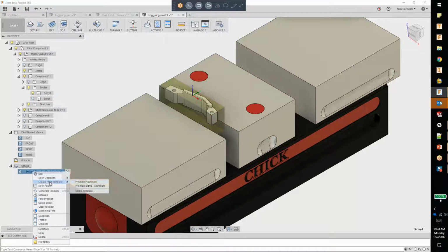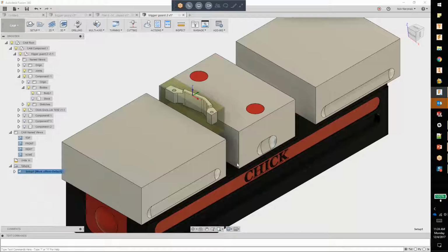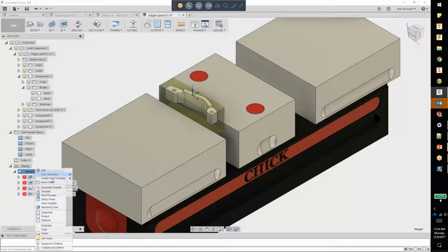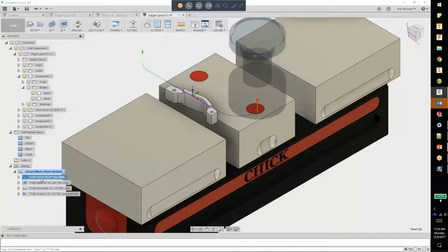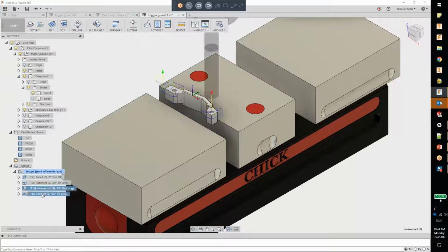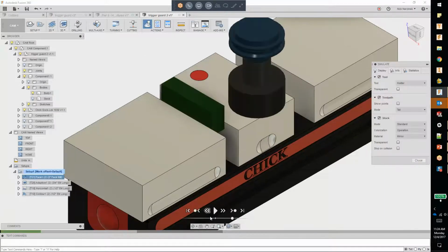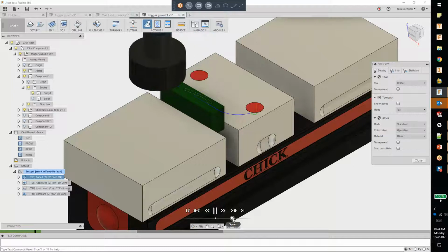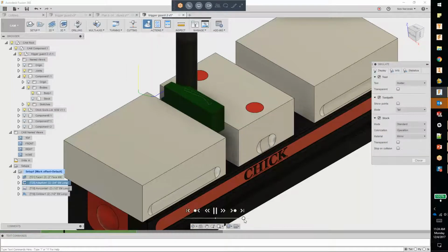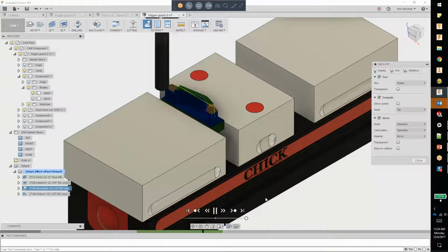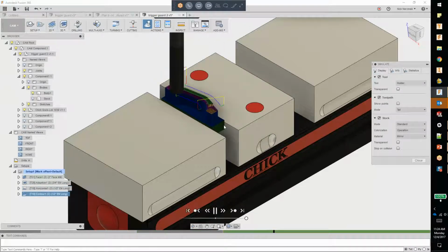And I've got some templates in here. I'm just going to create a template and regenerate those. It's probably not going to be all the toolpaths that are needed. We would need to chamfer and drill. I don't have those in there. But you get the idea. I got the setup now. I got those in there. I can simply simulate that out now. Speed this up a little bit. And I just have the information in my window that I'm working with. That's the important part.